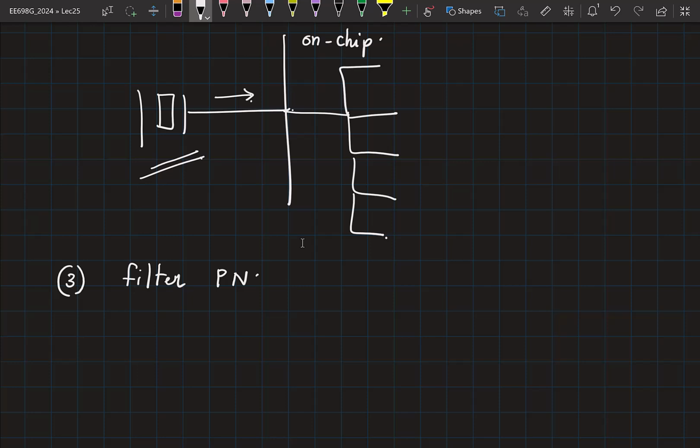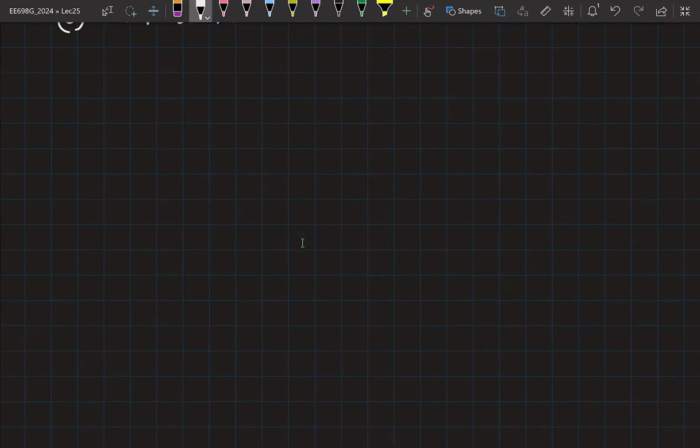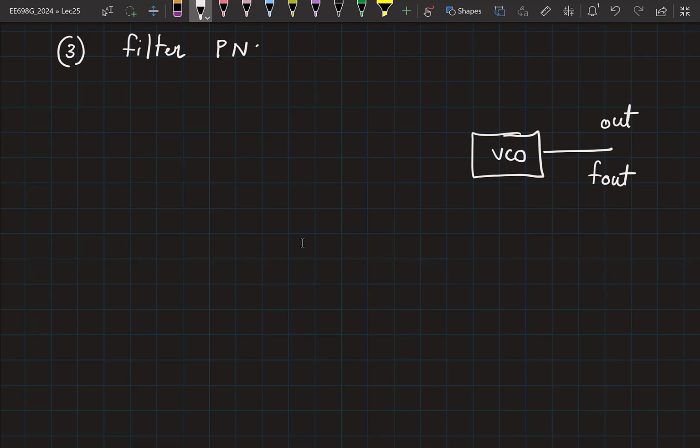So now let us get to building this system. So we have a VCO, right? Let me call this output as M out. It has frequency F out. What all components do you think should be there? So we have a reference signal with, let's say, frequency F ref. You have seen one time domain loop. So help me build this. You can use generic terms. What should be the first part here?